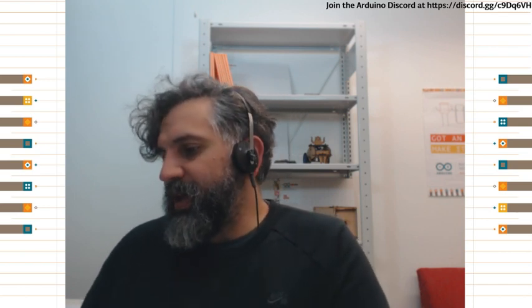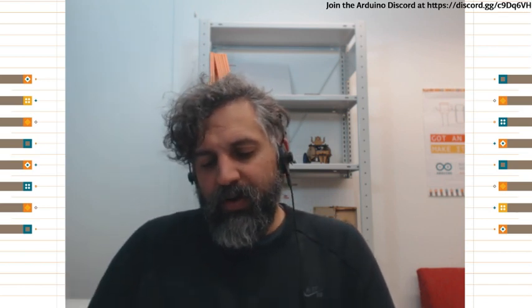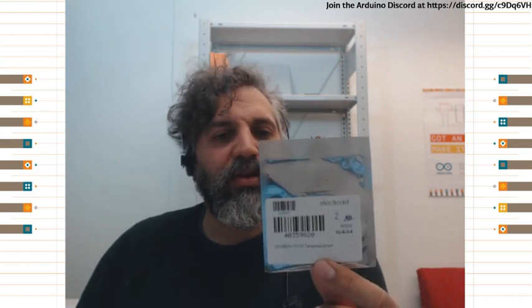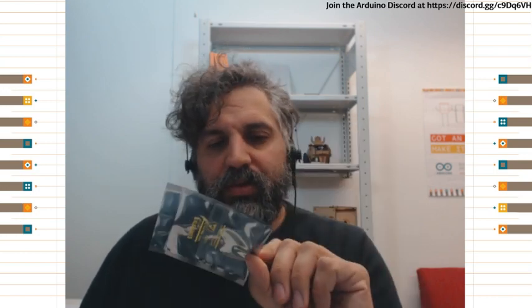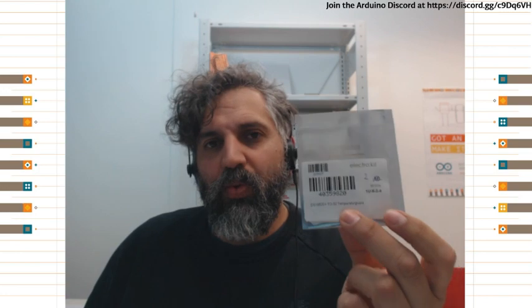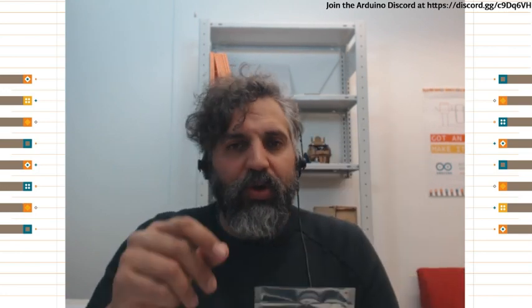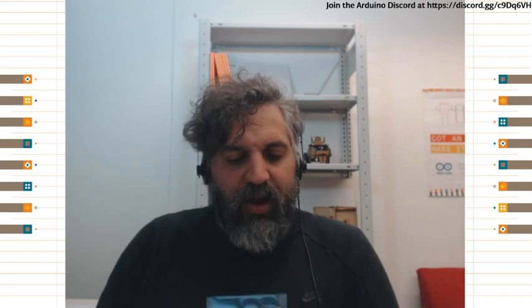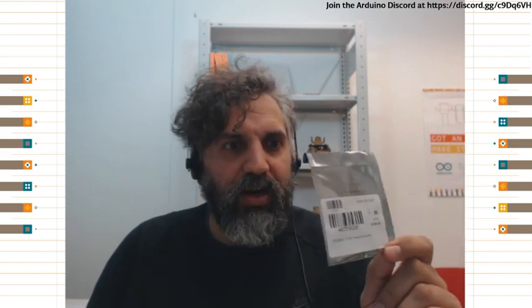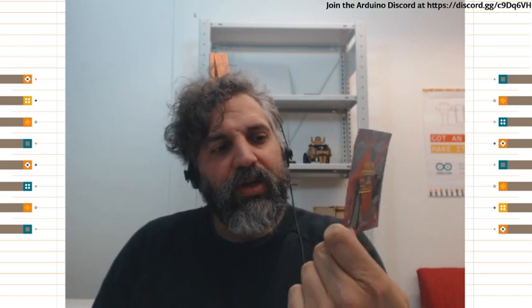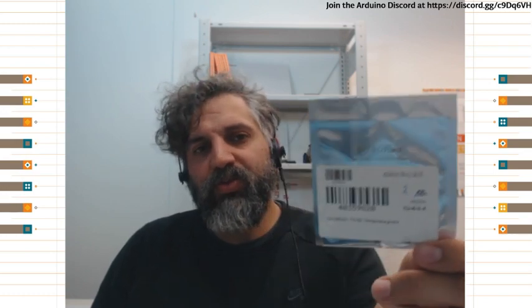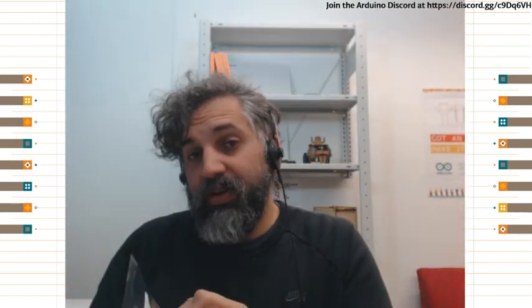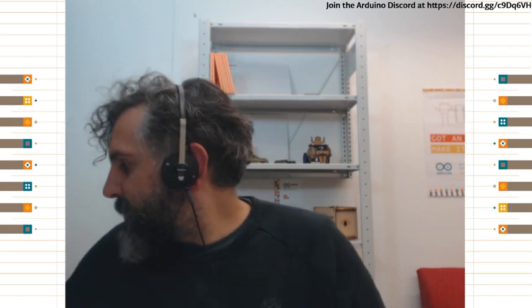Then we have a 1-bit temperature sensor. It's controlled through a 1-bit port, and it allows you to have a whole bunch of different sensors hanging from different pins in Arduino. Some people have used this to monitor their whole house with a single Arduino board and a really long cable. So this is the DS18B20, the next contestant for the list.